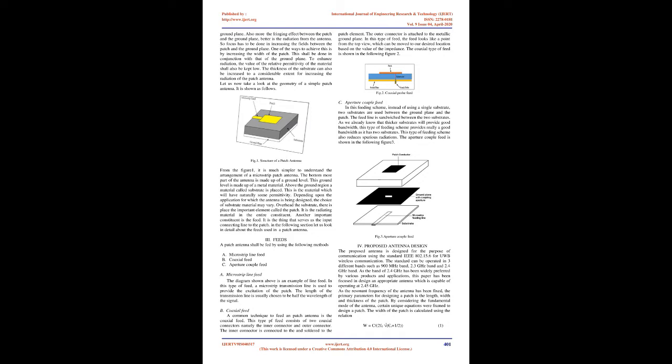2. Microstrip antenna. A microstrip patch antenna is a low-profile antenna used for a variety of applications. It consists of 3 main components, namely the ground plane, substrate, and the patch. The ground plane and patch are made up of metal while the substrate is made up of a dielectric material. The ground plane is placed at the bottom part of the entire structure. The substrate is placed above the ground plane and at the top we have the patch. The patch, which is a metal piece, is the main radiating element in the antenna structure.